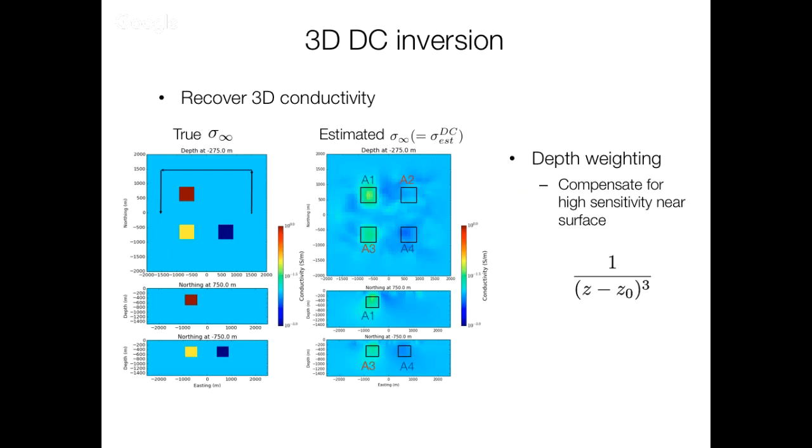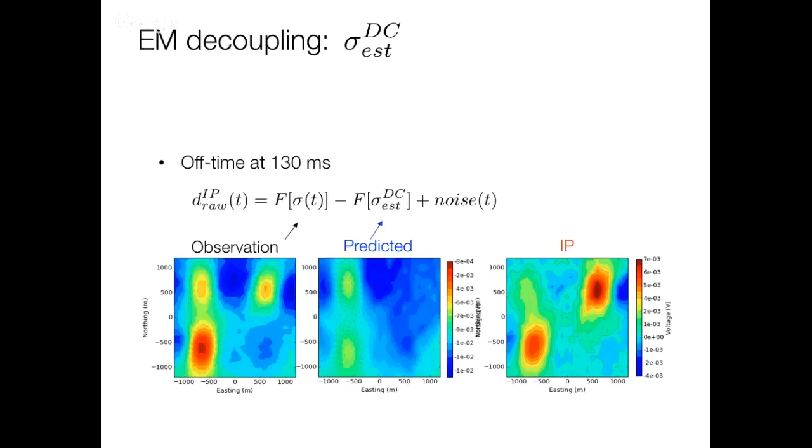Because we've got a gradient array, we only had like one transmitter, right? So we've got just one source, and then we had all these fields. So we're not exciting the bodies from multiple directions. It's more of just a gradient survey, and that really translates back to almost a potential field. So we need to have a depth weighting in that, otherwise everything can come right up to the surface. Anyway, it's a bit of a wrinkle.